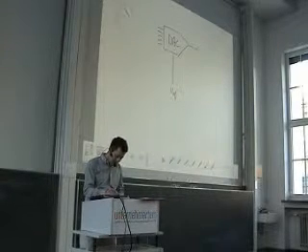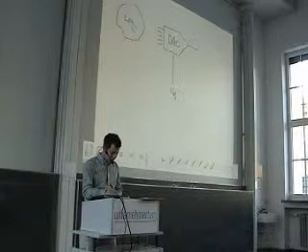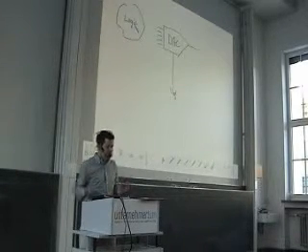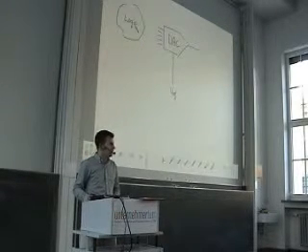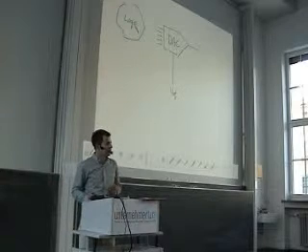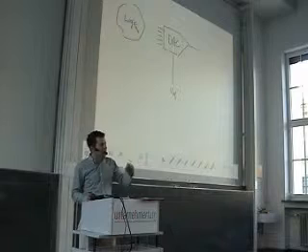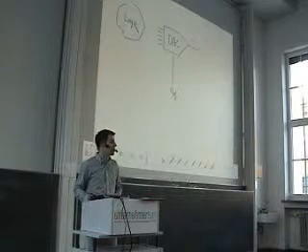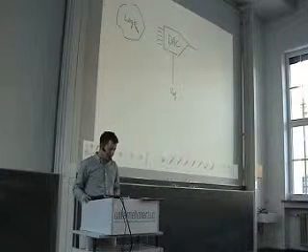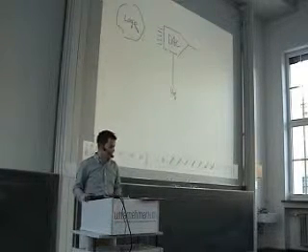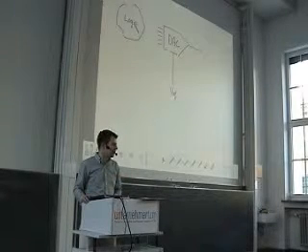And the input bits come out of a certain logic that computes the value for the DAC. In this computing logic, there may be a short path to one input of the DAC, and there might be a long path to another input of the DAC. And hence exactly this situation may occur that the switching times are different and these glitches occur.